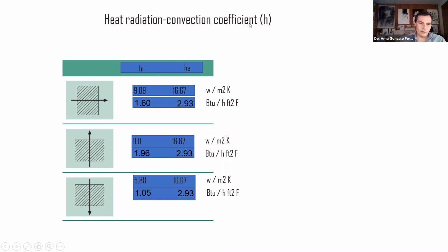It's not conduction, because conduction happens only through solids. It happens because the temperature of the wall and the temperature of the air are different, and then we have these small cells moving around it. That provides the wall with another thermal resistance that we didn't take into account last week. But this week, we are going to work with these coefficients,